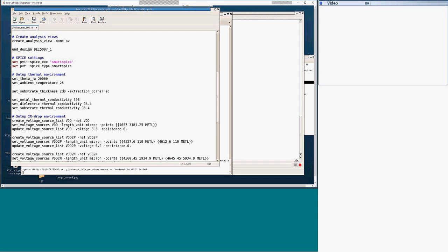See, it's not a problem. You see, 200 we use by default for smaller blocks. You can set it to 650. From my experience, bulk substrate volume, especially combined with the package resistance, doesn't have much effect on actual thermal profile. It may restrict or define uniformity of thermal profile, but in general, package resistance has much more effect than substrate thickness.